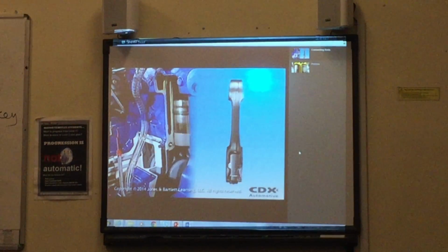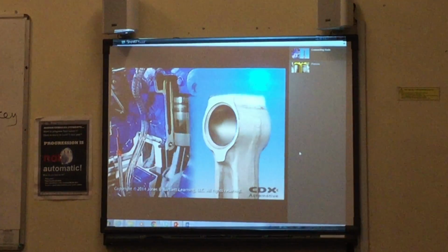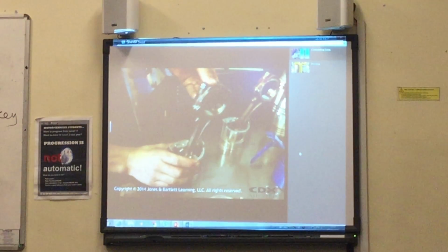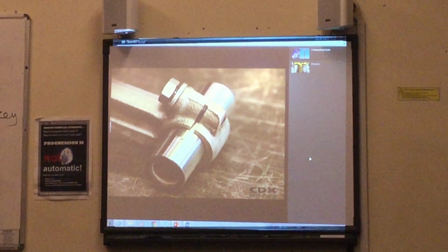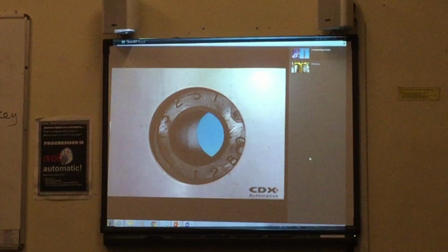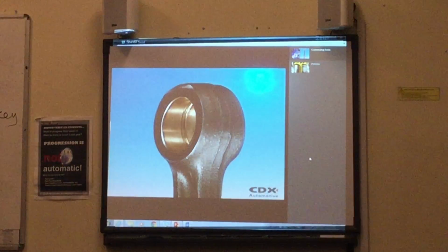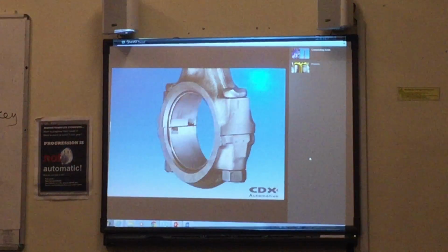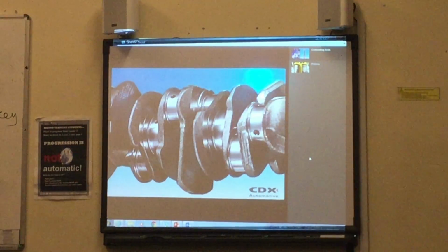The connecting rod connects the piston to the crankshaft. It is fastened to the piston at its little end by a piston pin, also known as a wrist pin. In some engines, the pin is a press fit in the small end of the connecting rod. In others, it is clamped to the connecting rod with a clamping bolt. Another method lets the pin float in both the piston and connecting rod, and it is held with circlips. There is a bearing in the small end of the connecting rod. The big end of the connecting rod has a detachable cap and carries two halves of the big end bearing. The big end is attached to the crankshaft at the crank pin journal.